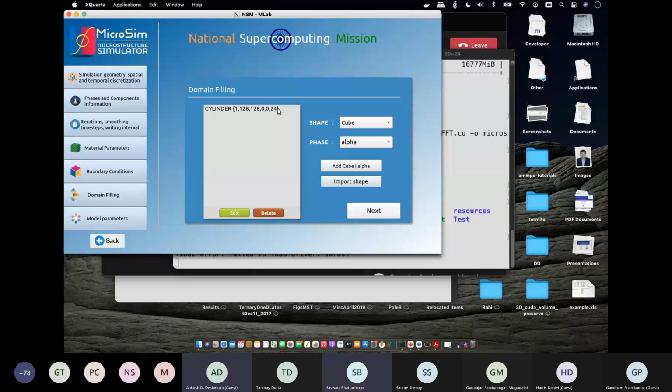You can also take a smaller radius, not a problem. But again, as Apik has pointed out in the previous talk, be careful that you should have at least 8 to 10 grid points, maybe 10 grid points is a better idea, at the interface. Whatever interfacial width you choose, whatever values you choose, make sure that you have 10 grid points at the interface.